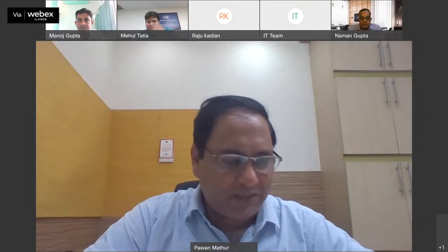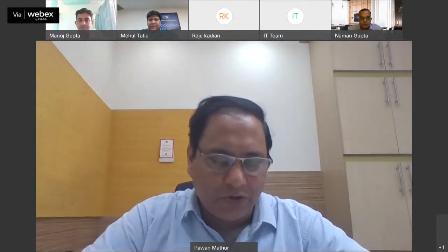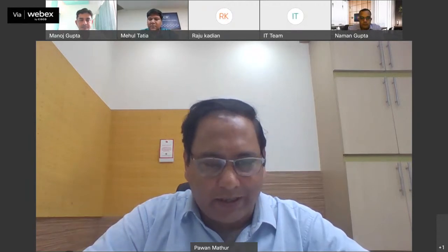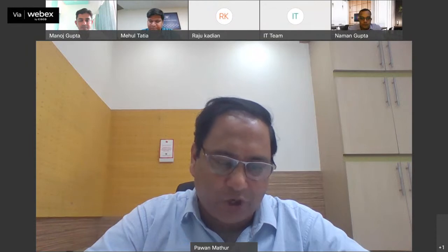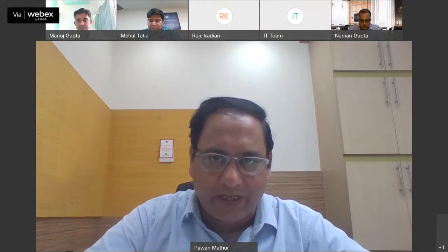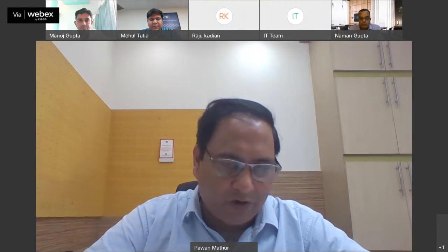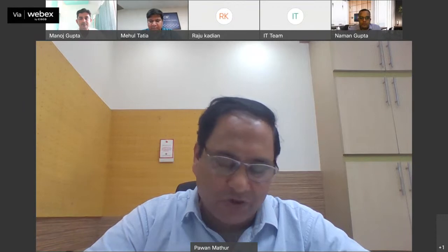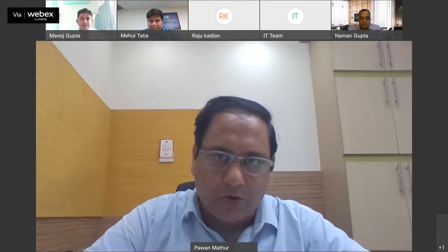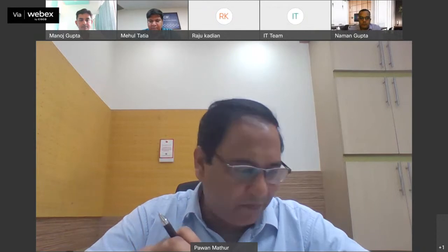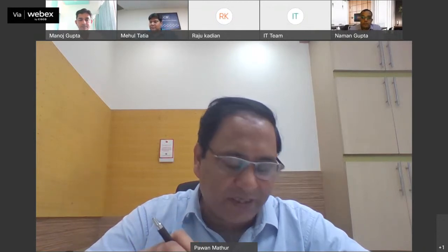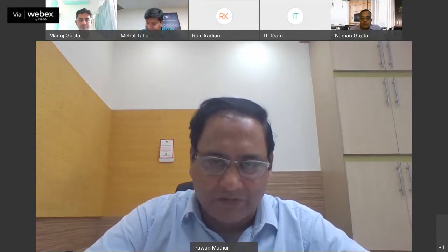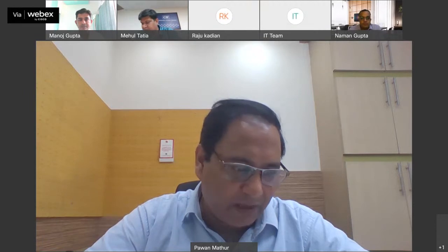Just to have the summary for all of us, Mr. Manoj told us first about air quality in terms of solid content, water, and oil. Because if we don't maintain the quality required for our equipment, then we will have losses at other places and maybe some equipment damage or breakdowns. Second, he told us the importance of energy, because he said 15 to 20% of electrical consumption in thermal power plants is due only to compressed air, which is true, and that is why this is very important.